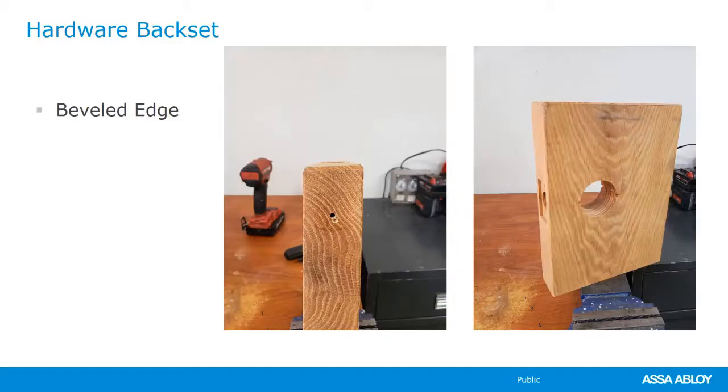So I want to talk just a little bit about the beveled edges of commercial doors. In the residential world, we don't see very many doors that are beveled, but in the commercial world we do, and that means that you have a high side and a low side on the door. If the installer is measuring for the hardware installation and they're putting the vertical center line, which we're calling the backset, if they're measuring for the backset and they're measuring off of the low side or they're measuring off of the high side for that backset, well, they're going to be off a little bit.